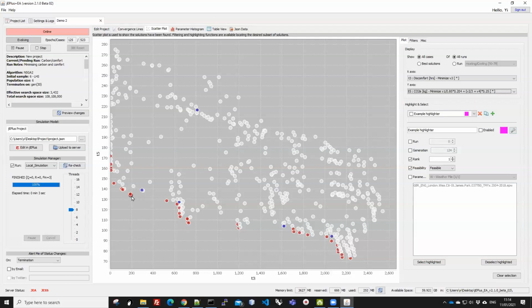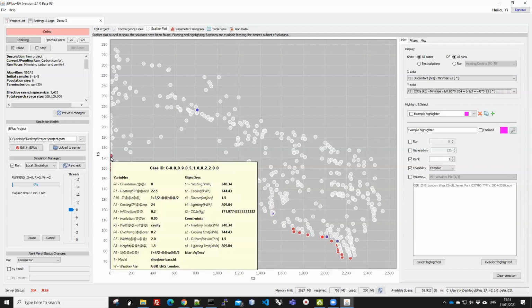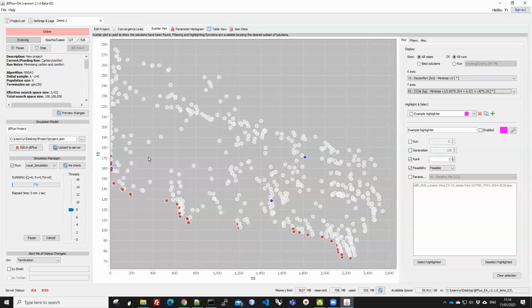But for comfort, actually, what we are looking for is not absolute comfort scenarios, say absolutely no discomfort hours. This is not what we are looking for, because in reality, you just can't get everybody to feel comfortable. Whatever environmental conditions you provide, there will be some people who find it uncomfortable. So that's impossible to achieve and quite pointless to do as well, because even if you can find one, you find the cost will be too high.